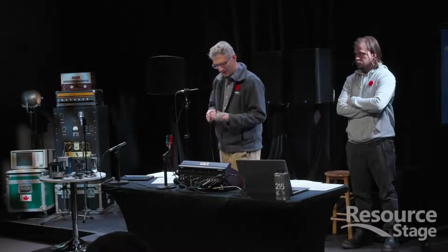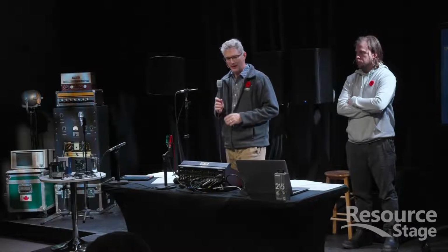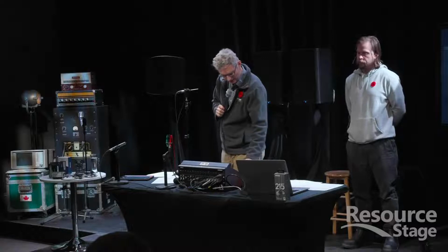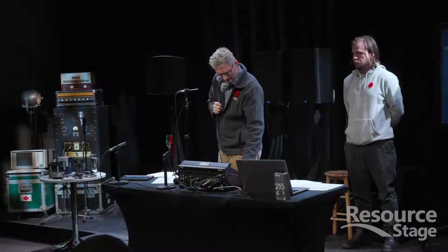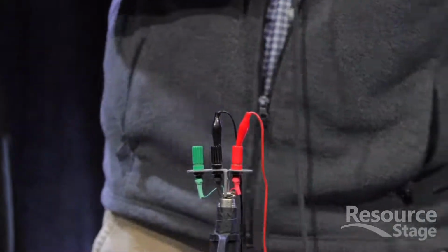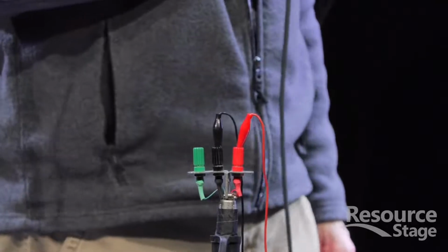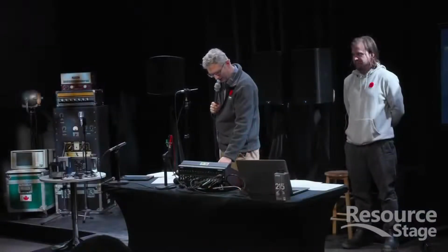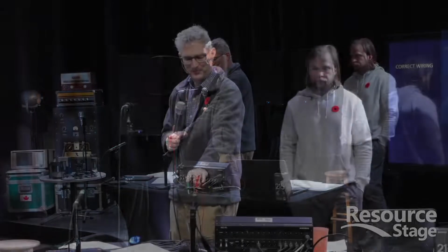Now, let's take this particular microphone. This is a Shure Beta 87A, which is a condenser microphone. And we're going to do the same test here. We'll unmute that. So all 3 conductors are working, and it's working just great. Sounding really good. If we disconnect pin 1, and then we unmute it, it's not working at all. Nothing. Nothing is there. Even if I turn up the faders, nothing is there. And that's because this is a condenser microphone, and so the phantom power is being sent down pin 1 to pin 2 and 3, and so the circuit isn't completed, so we don't have the power to do that.